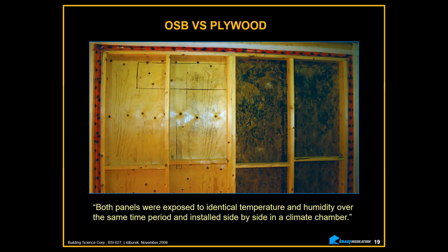No worries. Yeah, and that's something I can tell you just from doing the field training. Can you hear me, Rick? From the field training I've been doing, the number one problem I see in residential construction in Texas is in relation to the weather resistive barrier. There isn't a specific inspection mandated by code for a weather resistive barrier. Kind of blows my mind because that's just going to be one of your main failure points.